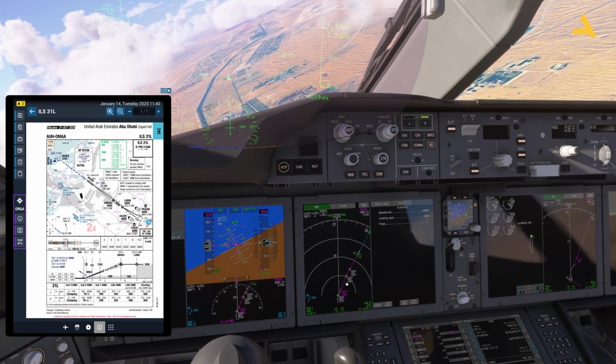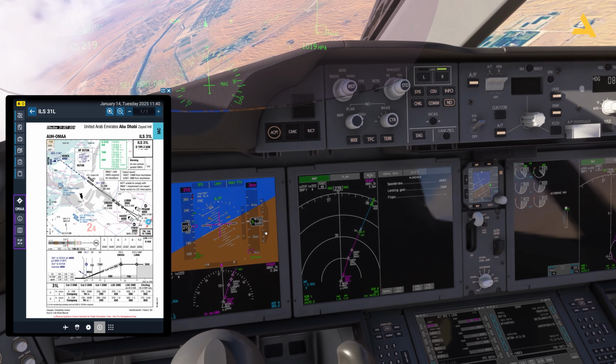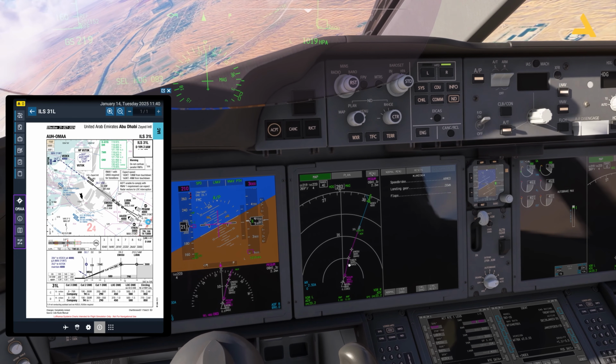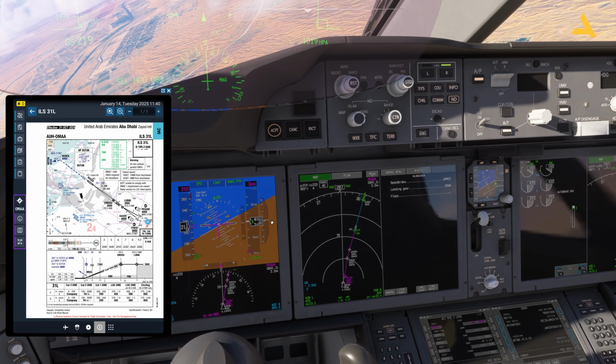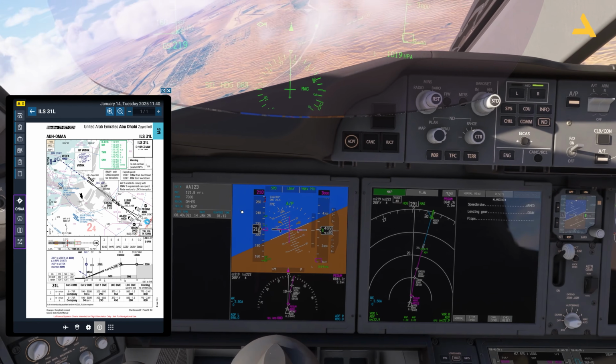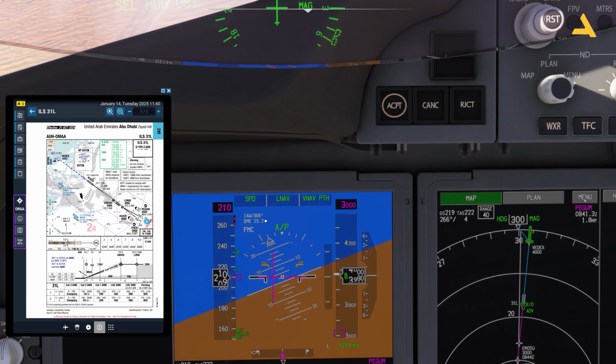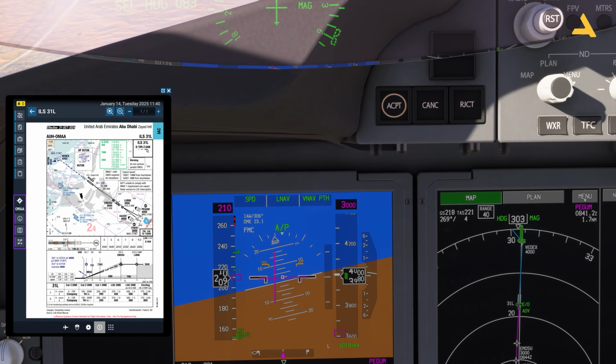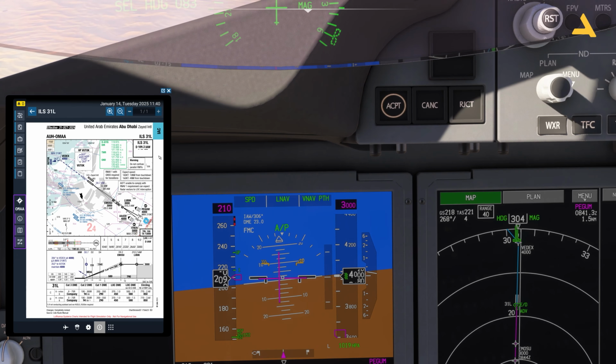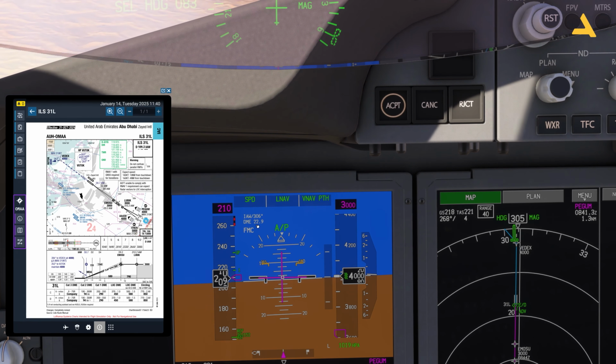Now it will level off, and it will just keep on flying at this altitude till the time it's near this point, Lubeck, and then it will descend to 3,000 feet. And right now you can see the ILS information, IAW, this is the identifier. 306 is the heading, and the distance is 22.9 nautical miles.